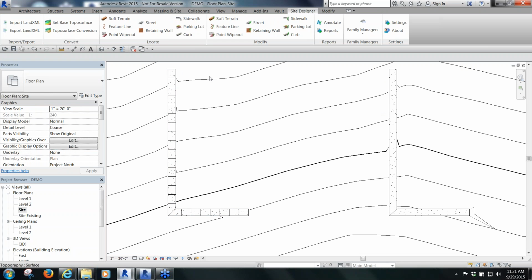That's because my model lines that created this sidewalk were actually 5-foot segments. You'll have a little more success breaking it out into segments like that, especially if you've got varying terrain. It'll break it up a little more intuitively. So the model lines were just one continuous sketch.